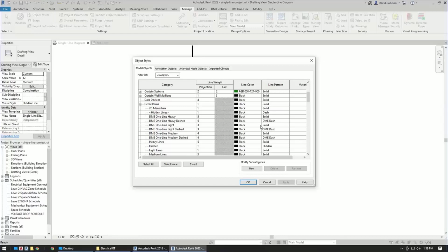In the same way, we've got the line patterns where you've got solid and dashed lines. We define a dashed line pattern. If you have another dashing that you want to use, you could change it out here. But the settings here, when you put something in, if it's using one of these line types, it's going to use what you've already defined. So you can define it in your project, in your template, and then when you pull in our stuff, it'll know to take the line types we have and map them to the settings that you've set.